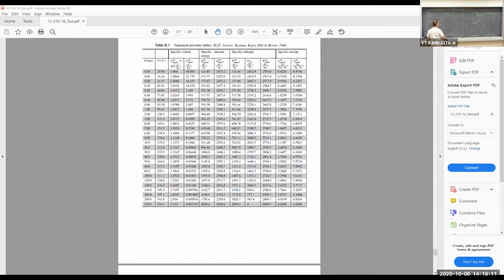So actually, we're not going to get an internal energy to get state 2. We're going to get a specific enthalpy, H2. That's fine. If I have H2, I can get a quality. If it's a saturated mix, it doesn't matter. But I'm running into similar problems here. I don't have the mass of the H2O. I still don't have the mass of the H2O, and I need that to get delta S. Maybe I should calculate the mass of the H2O.